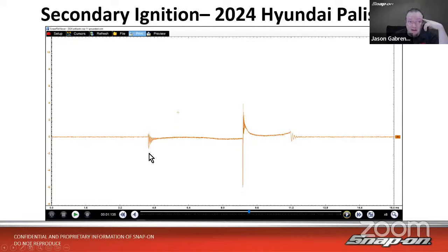You can definitely see good detail on dwell when it charges. There's dwell there. And then the firing line, oh, it goes negative to positive. So that's unusual, but that is just how the pattern presented itself on this vehicle. So I do have a firing line, I do have a lot of oscillations here, I do have a spark line as well. It's fairly level, and I do have some coil oscillations there. So it was able to get me a pretty darn good pattern, at least to analyze what's going on.